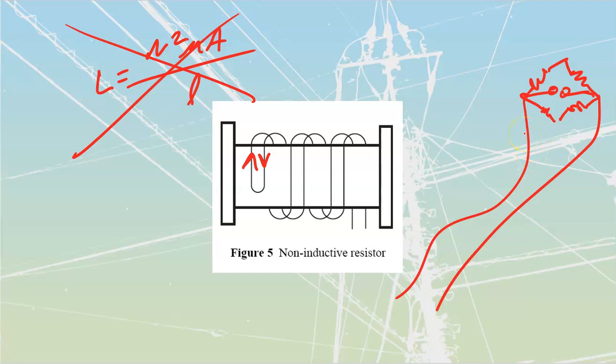They're also called bonded metal strain gauges. The wires that come out of here are going to be long, but you're not allowed to cut them off. Most load cell manufacturers straight up outlaw it because it changes their readings. So instead, what you need to do is bundle them tightly.